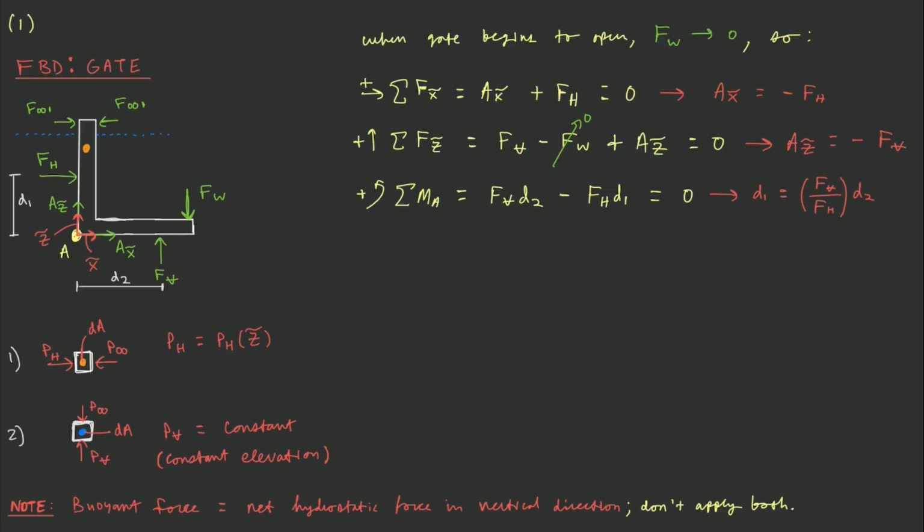So you'll end up seeing a pressure distribution that looks like this on this face that increases with depth, and the pressure distribution on this face will be a constant uniform pressure distribution, very similar to the constant uniform pressure distribution you see from the atmosphere on the opposite face on the same side. So what we want to do here is establish what we mean by net pressure.